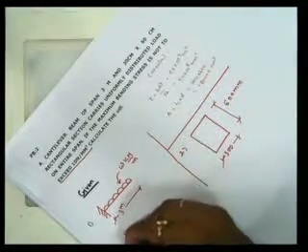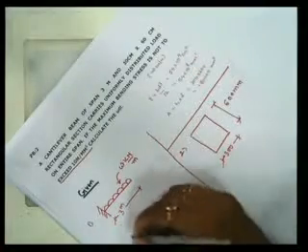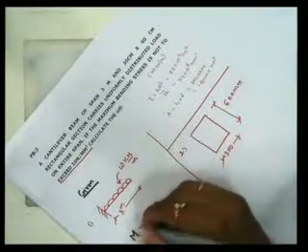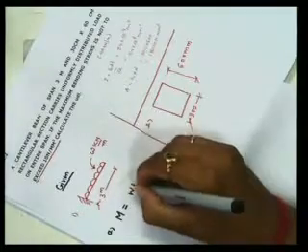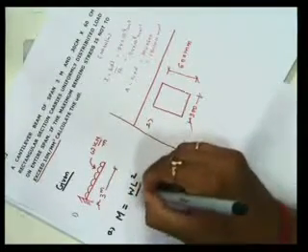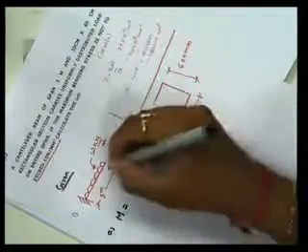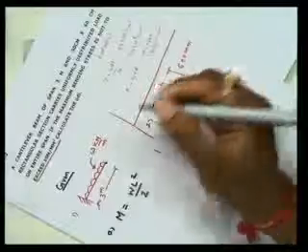Now first I will have to calculate from my loading diagram the value of maximum bending moment. Again it is standard: a cantilever beam subjected to a uniformly distributed load. So your standard formula is WL square by 2. If you are unable to remember the formula, we know that at the free point it is 0 and at the support it is maximum.